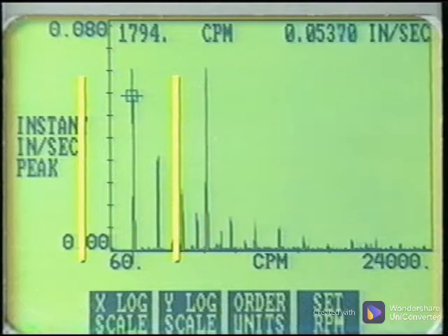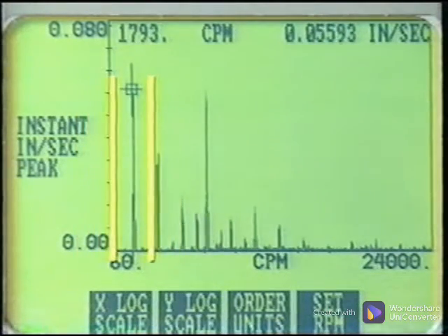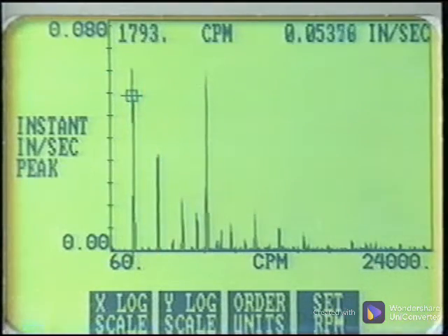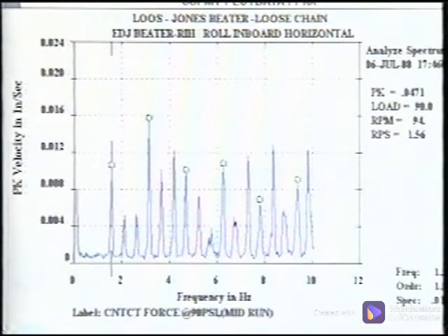Erratic or unstable phase measurements can be associated with rotating element looseness. During normal phase measurements, if the phase is very unsteady, not simply slowly rotating or staying within a certain window, then check the spectrum for peaks near the 1x peak and verify that the bandwidth is narrow enough to include only the 1x peak. Also check for a looseness spectral pattern, that is, multiple harmonics of the turning speed peak.